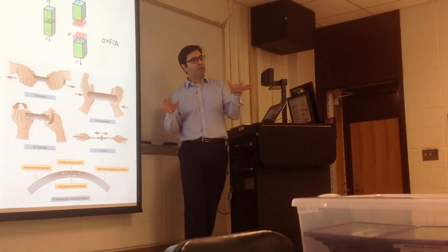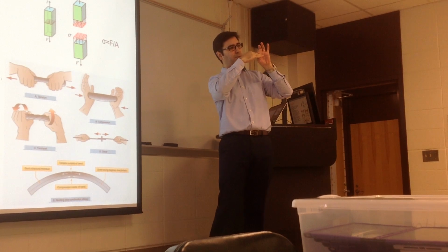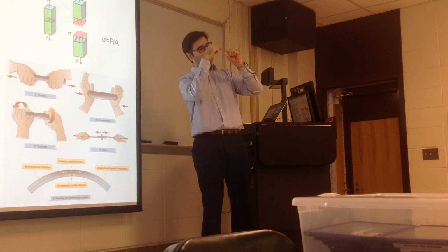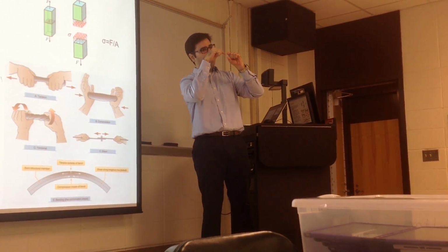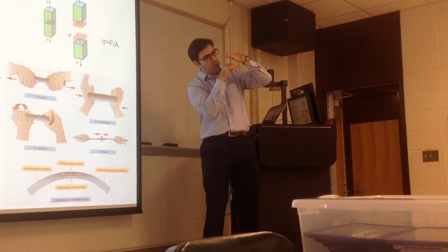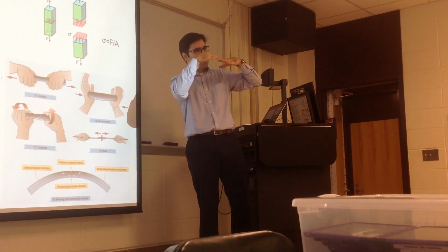Then shear. Shear is a little more complicated. So you may have one plate and another plate joined by a rivet. You push one in one direction and the other in the other direction. If you look at the force that the plate is exerting on the rivet, on one side it's going one direction, and then when you change from one plate to the other, it's going in the opposite direction. So it's generating this shear force.